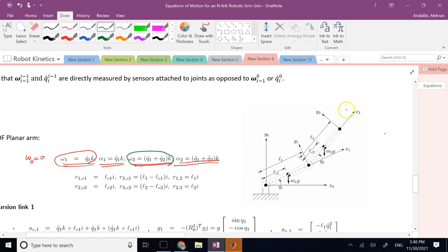That's right, because the robot is too simple. If the robot is really complicated, it's not so easy to do all of those computations visually. If everything is not planar, if you have a combination of revolute and prismatic joints all together, then none of these computations is as trivial. So you have to go through those recursions and get yourself all of the accurate calculations.